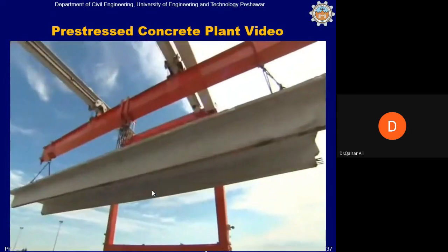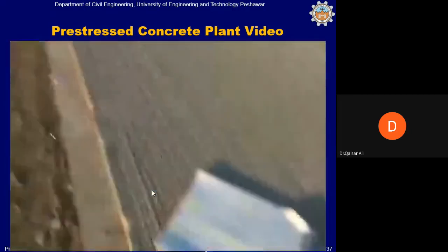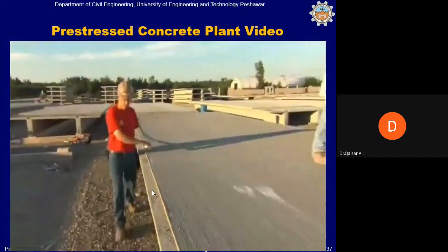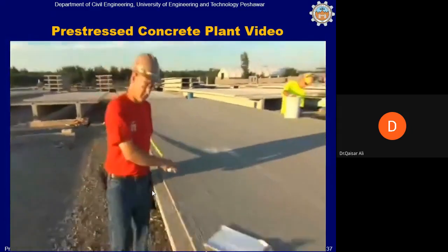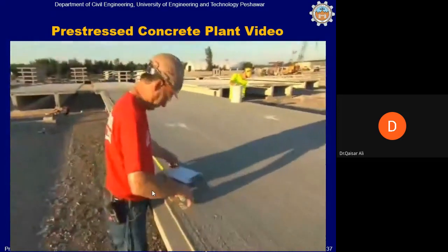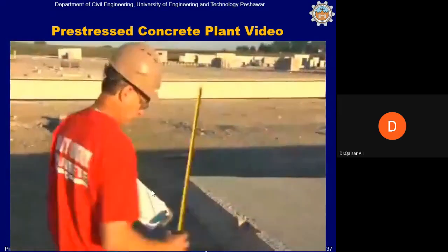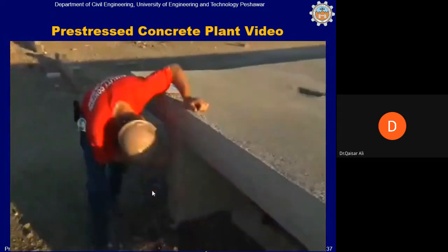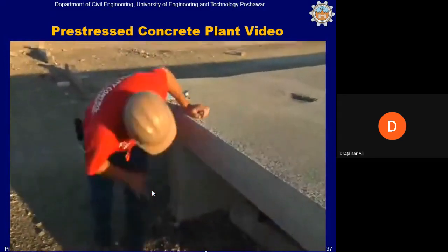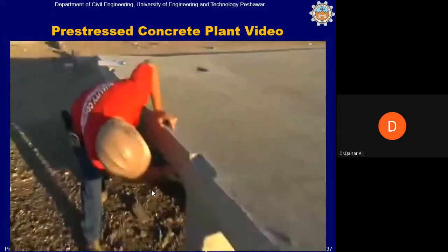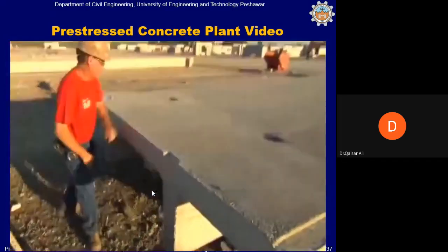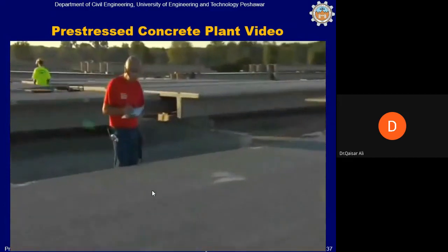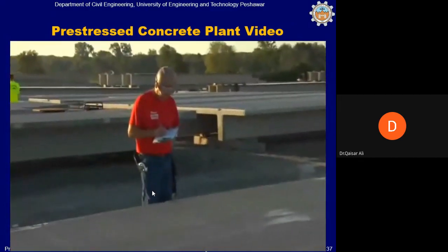When I first get back there, I go and check the length of the piece, verify that it is within a tolerance of probably a quarter inch or so. Check the width, we check the vectors, we check the electrical blockouts. I do a visual for any type of discoloration in the stems underneath the piece, any type of surface cracks, bug holes, just do a complete visual. Any defects are noted so that repairs can be done before shipping the tee.